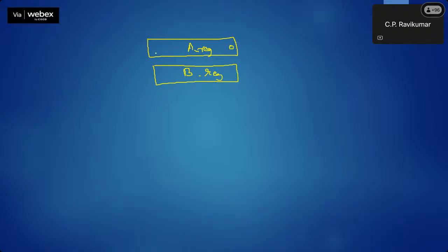This is 0 to 4n minus 1. So for example, if it is 8 BCD digits, we will have 32 bits. So initially, we load this from the input that is given to us. I think we have called it A in, and we have called this B in.